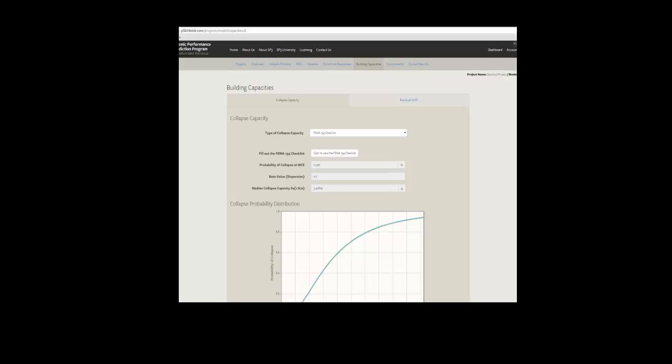I think maybe I'll turn this question over to Ron, but the guideline is to use the 154 fragility, or the checklist to get the fragility. The reason for that is because the fatality and injury rates that are used for the thresholds have been made consistent with FEMA 154 checklist results.